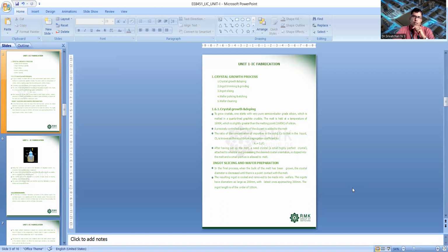So the melted silicon gets deposited in a cylindrical shape because it is rotating, forming a deposition of shiny pure silicon as the seed is moved slowly away from the melt. It forms a drum-like or cylindrical structure, and that is called the ingot.